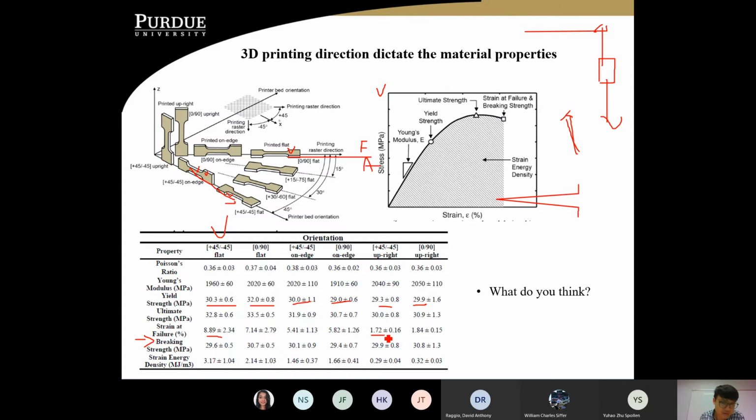So here I want to bring us back. To answer if anybody has that question in their mind: yes, PLA, the material that we're using, yes, the strength is weaker, but you also have to consider how the 3D printer, whatever facility you submit your STL file to, prints it originally. The way the direction is printed actually matters for the final performance of the material.